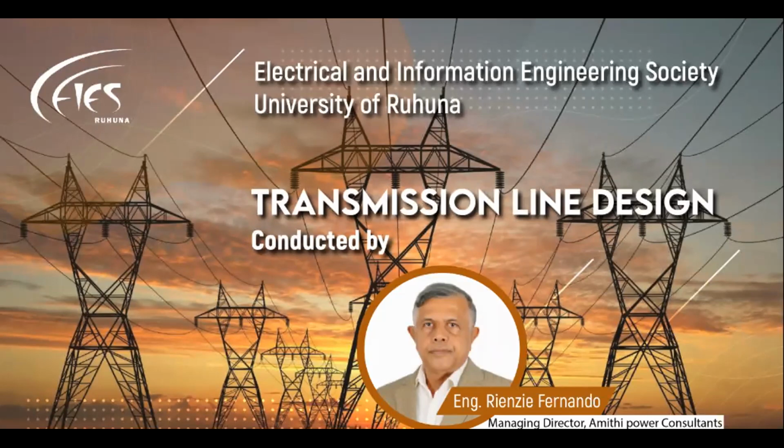Are there any specific ways of earthing a tower line? Required value for earthing? Now, the required value of earthing is always taken as 10 ohms, and it's always measured with a high frequency earth tester, and that is supposed to be the surge impedance of the earth.